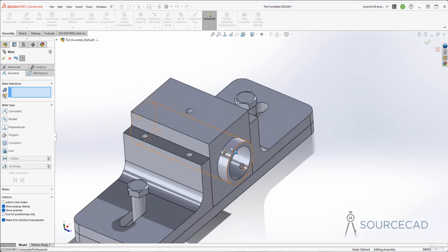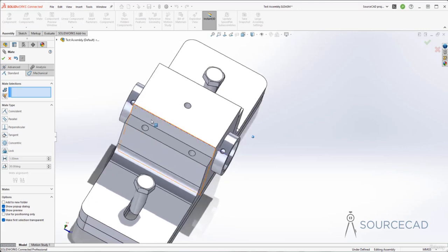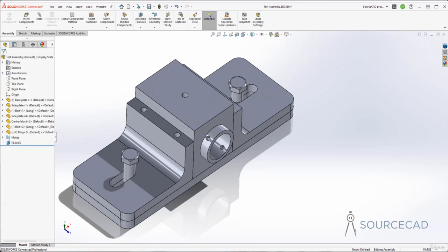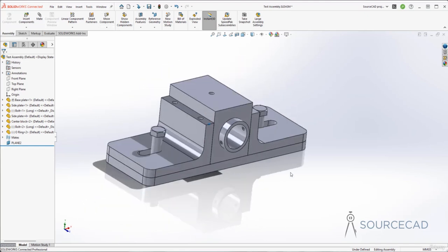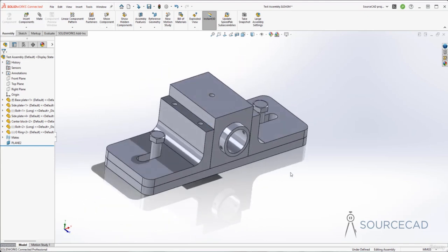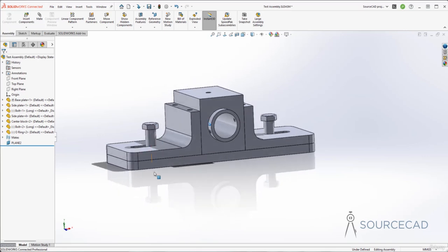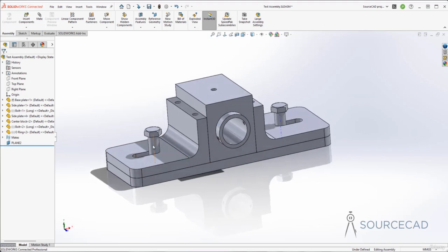All right, so now it will move out only up to 5 units, and the same is true for this side. And now if you try rotating it using this groove, it will rotate very easily. So maybe I'll just click OK to exit out of this mate option, and then we'll try rotating it, and here, as you can see, it will move very freely. All right, so that's added. Now let's talk about adding a few mates right here. So here in this case, we want to add a washer and then a nut right here. So let's start with washer.